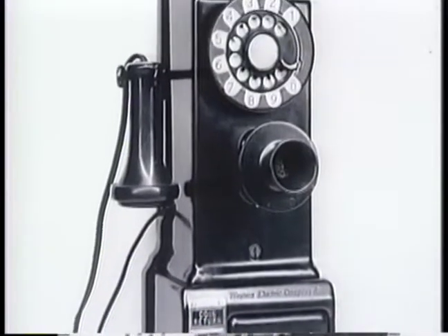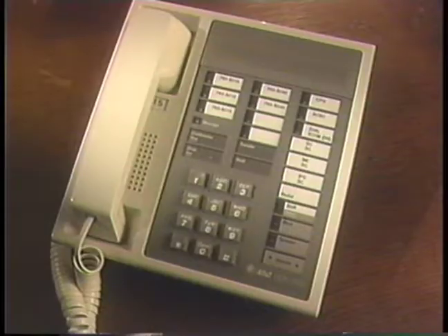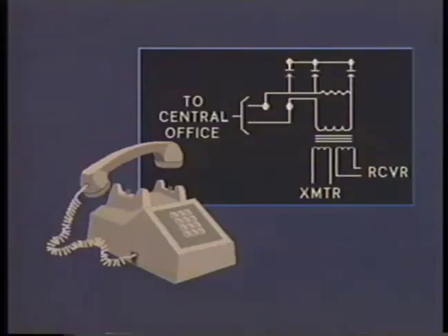At the other end of the handset is the receiver. It's basically a speaker that converts electrical signals into sound. It's similar to any other speaker that you would find in a radio or stereo. In these early-style telephones, the receiver hangs on a switch hook. On new telephones, however, the receiver is in the handset. Both the receiver and the transmitter connect to the hybrid coil. The hybrid coil combines a 4-wire circuit in the handset into a 2-wire circuit that connects to the central office.